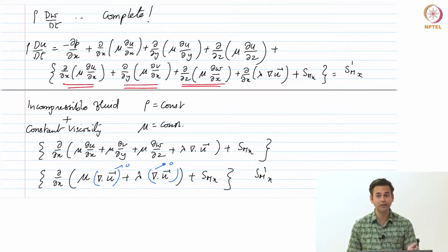It would have these extra terms in case you have a compressible fluid or a non-constant viscosity. In those cases, your source term is not just coming out of the body forces, okay. Very good. Now this looks good. Of course, if you look into some textbooks, they would use lambda equals minus 2/3 mu, in which case you have 1 mu here and minus 2/3 mu, which gives you 1/3 mu and so on. That is some simplification, but nonetheless that term will go to 0, okay.